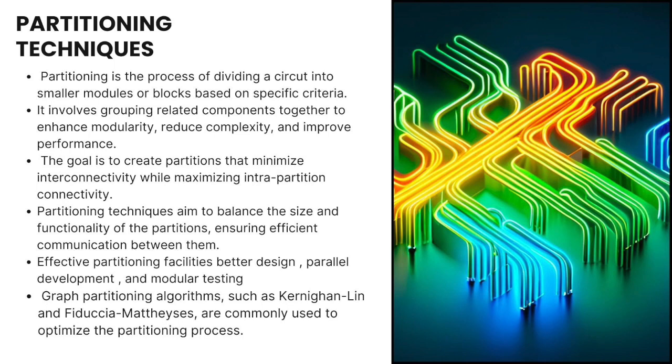So here the question arises, why do we need to partition? The main goal of partitioning a circuit is to minimize interconnectivity while maximizing intra-partition connectivity. Here, interconnectivity means the connection between two nodes which are not in the same partition, while intra-partition connectivity means the connection between nodes of the same partition. Effective partitioning provides better design and parallel development.